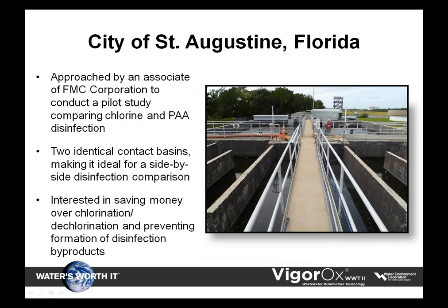The city was approached by an associate of FMC Corporation to conduct a pilot study comparing chlorine and PAA disinfection. Our wastewater plant has 2 identical contact chambers, making it ideal for a side-by-side comparison. So at the time, we decided we were interested in saving money over chlorination and dechlorination, and also preventing the formation of disinfection byproducts in anticipation of future stricter regulations.